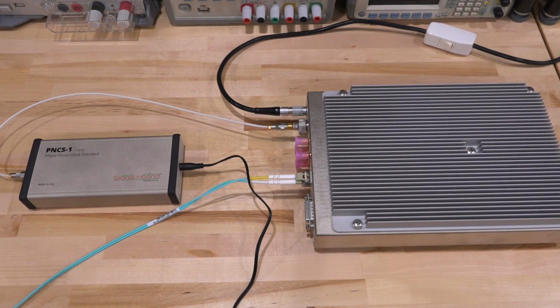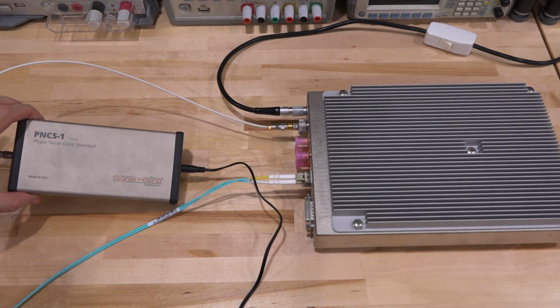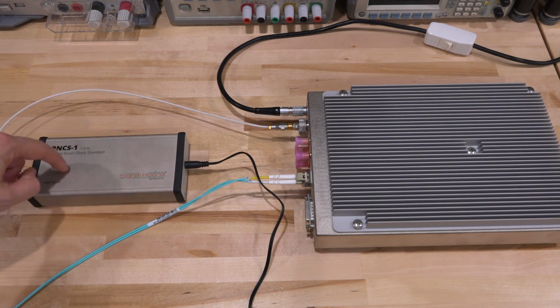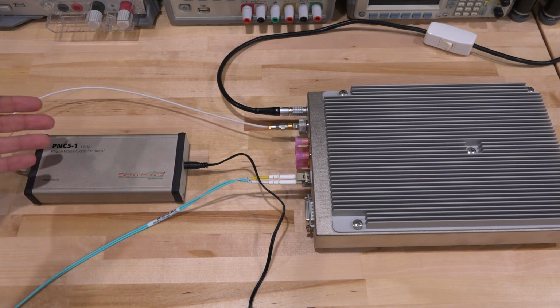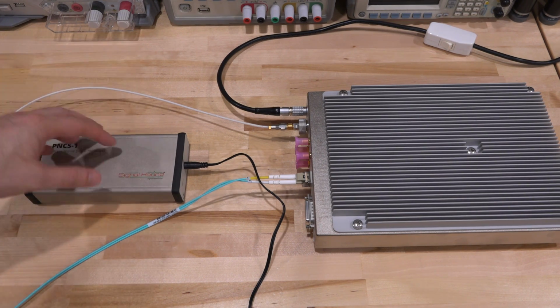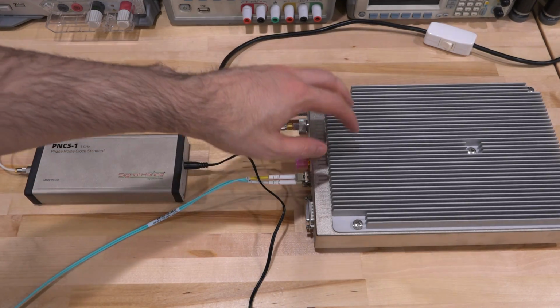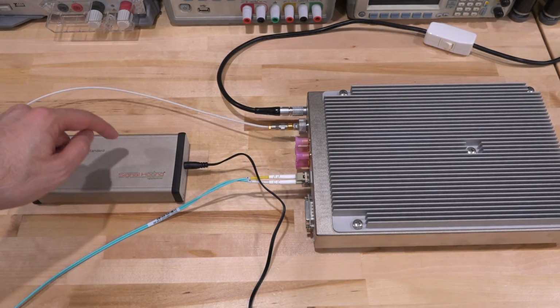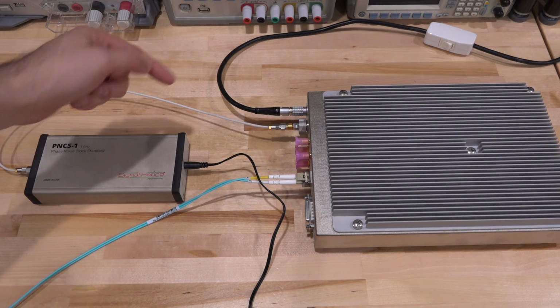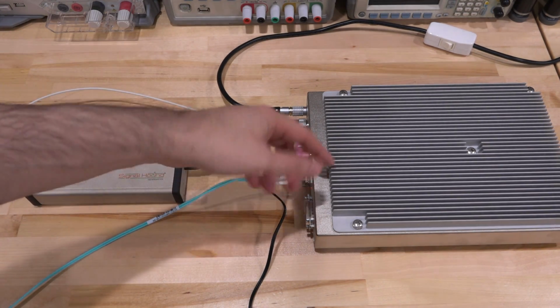Well, we may as well use the phase noise personality as well and measure the phase noise of the instrument itself. I'm going to use the Signal Hound PNCS1. I've done a full teardown and review of this unit as well. This is a 1 gigahertz phase noise standard, so it has an exceptionally low phase noise. Whenever you connect it to pretty much most spectrum analyzers, you will be able to measure the spectrum analyzer's internal phase noise because this one is so much better. So we have it directly connected to the input. This is at 1 gigahertz, and now we get to go and use the personality and find out if this thing meets its specification.